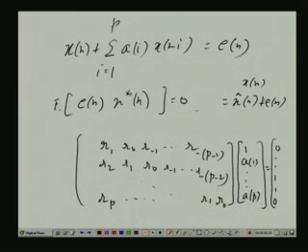Alternatively, in the case of AR modeling problem, you view x cap n as the prediction or orthogonal projection of x n, not on the space spanned by just the past p samples, but by all past samples. That is x cap n, and the error is E n. E n is orthogonal to this x cap n by the same logic, and you put them back here. You once again get E of mod E n square, which is a variance.